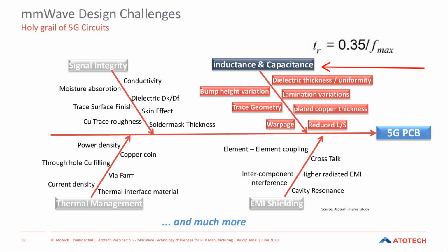Efficient transfer of energy is one with a minimum amount of reflective loss due to impedance mismatch, as well as the amount of resistive loss due to mechanisms such as skin effect. So inductance should be kept as low as possible for efficient operation, and this is associated mainly with the design.